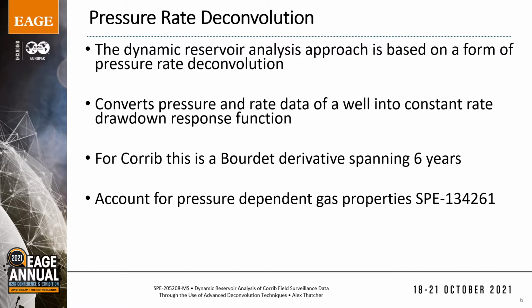Pressure rate deconvolution can only be used with the well data that are consistent with the principle of superposition. In our case of gas reservoir, gas properties depend on pressure, and this makes the problem of fluid flow in the reservoir nonlinear and inconsistent with superposition. However, we apply pseudo-pressure and material balance pseudo-time transform to the well pressure and rate data.